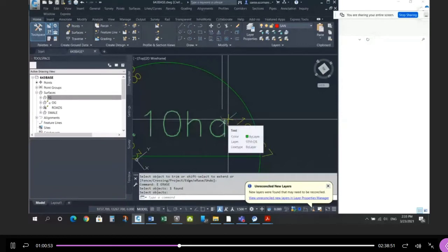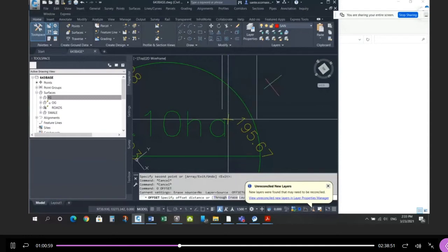You want to draw a catch basin, I'm going to make a copy of this line so it's parallel. I'm going to offset it 1 meter. Bring it here. Offset the back, draw a line perpendicular. Offset that 1 meter, and I get this 1 meter square. Close. It shouldn't be wide. Width of 0. So there's my catch basin. 1 meter by 1 meter.